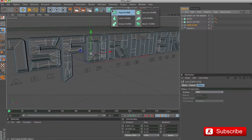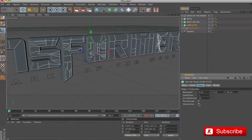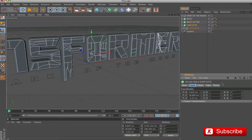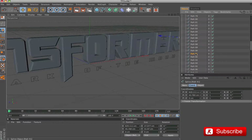We select the caps cuts layer, and apply an extrusion. Depth, to 4.25. In Coordinates panel, we insert in the Z position, minus 4.25. As we can see, the E letter has an extrusion problem in some paths. We select the paths from 94 to 97, and activate the Selection Points tool.